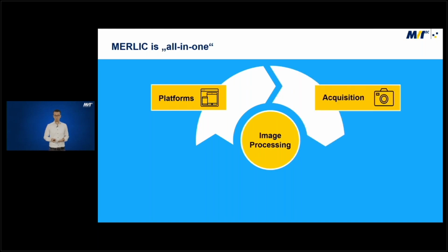Starting the application is always the first step, the image acquisition. And that's the reason why we have our Image Source Manager, which is completely separated from the image processing part and is serving all you need for setting up your camera system. The live image, setting up the configuration, the different kinds of hardware trigger modes. And with our Image Source Manager, we're providing the industrial standards for image acquisition, like GigE Vision, USB3 Vision, GenTL, and read image from file.